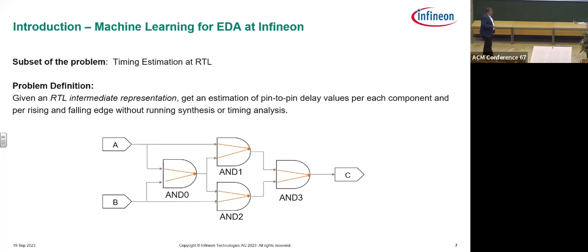We do a fast block-based STA. Block-based STA is a linear time algorithm, so we can run it easily. The good thing about linear time block-based STA is that it gets slacks, and with the slacks we can identify critical components where we can do a rearrangement, whatever. We can do a chain tree transformation. We can do an arithmetic retransformation if we know where we have to start.